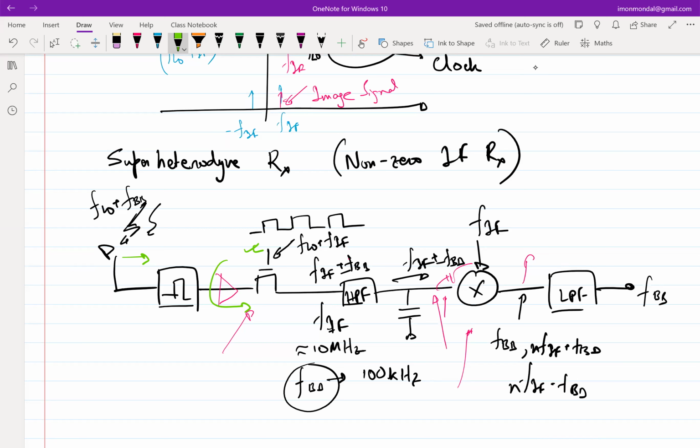Then based on some sort of filtering after mixing, I can get rid of the unwanted LO injection, and then we can do some filtering later on to bifurcate the junk that we are putting into our signal chain and distinguish it from whatever we want to receive.